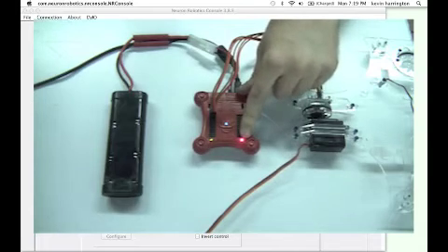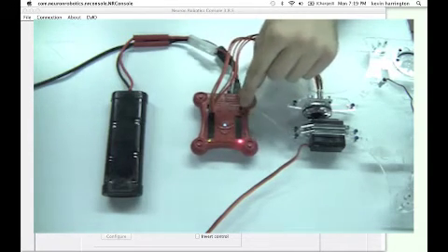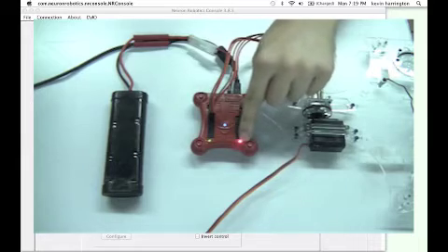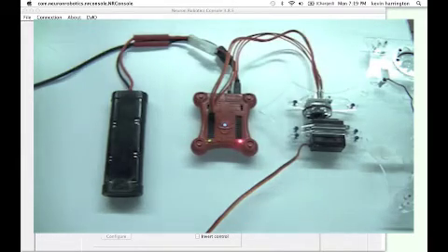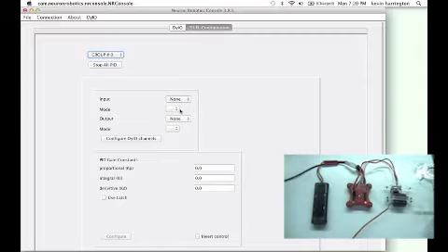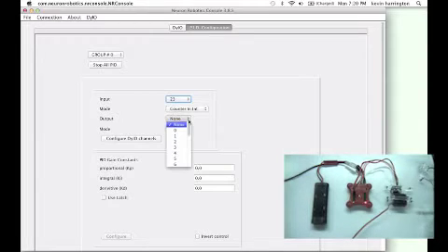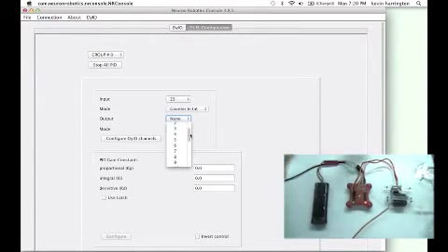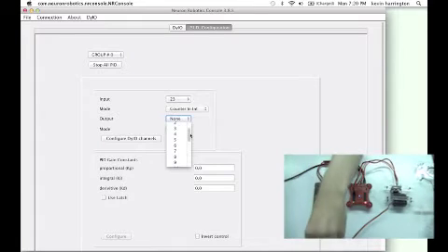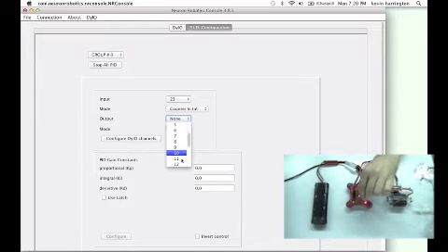Now you'll notice that the LED on the bank that is set to motors has gone from orange to red. You'll also notice that NRConsole notifies you that the battery has been connected. Now we can begin configuring our PID controller. Our input is going to be channel 23. Our output is going to be channel 11.